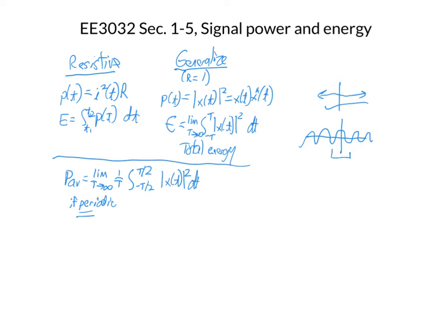And as I expand it out, the average power is going to change a little bit, but by the time I get out to 2 complete cycles of the cosine, the average power is going to be the same because I'm going to take that cosine and square it, and I have now twice as much energy because I have 2 cycles instead of 1 cycle, but I also have twice as much time, so the average power will be the same.